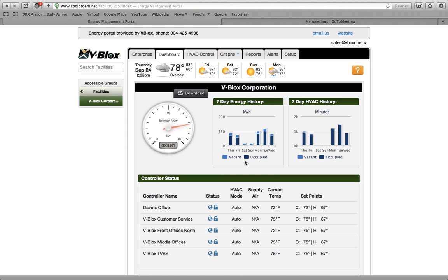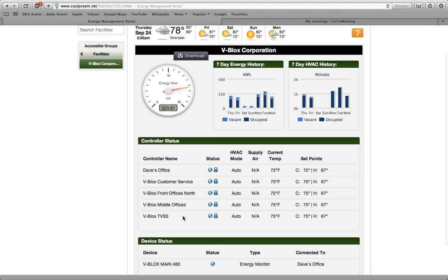And remember, on the screen here, you're looking at 5 air conditioning units. If those 5 air conditioning units are running 60% of the time, that's about 5 hours a day each. But you're closed 15 hours, and they're running anywhere from 3 to 4 hours while you're closed, and 12 to 15 hours over the weekend. Your runtime on air conditioning while you're closed is almost as much as when you're open.